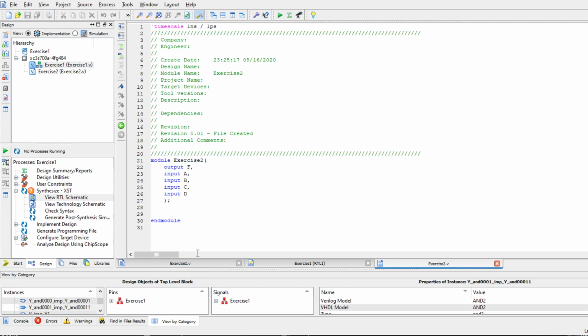All right. So after that, just like what we did earlier, we're going to assign values. So assign F, which is our output, is equal to, okay, B and D, or, okay, then close not, then close parenthesis B or C. So this is actually the same. You can actually distribute that one. There's no problem. You can also do that one. All right, then plus. Sorry, that's or. Do not forget that's or, not plus. Not A and C, not, and not D.